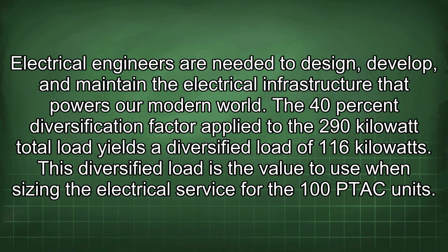The 40% diversification factor applied to the 290 kilowatt total load yields a diversified load of 116 kilowatts. This diversified load is the value to use when sizing the electrical service for the 100 PTAC units.